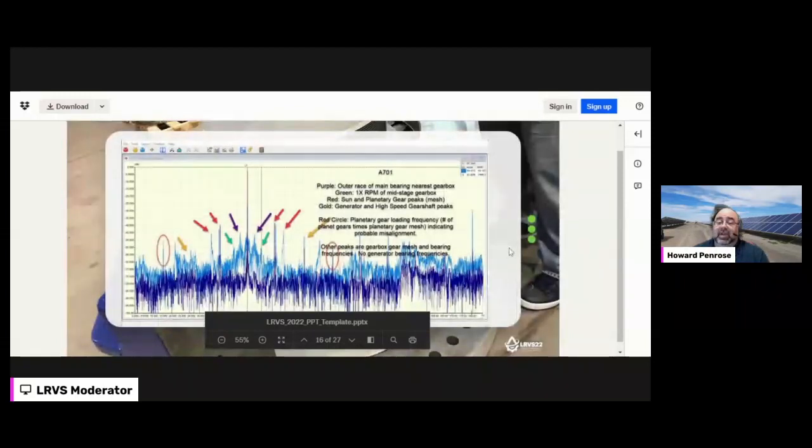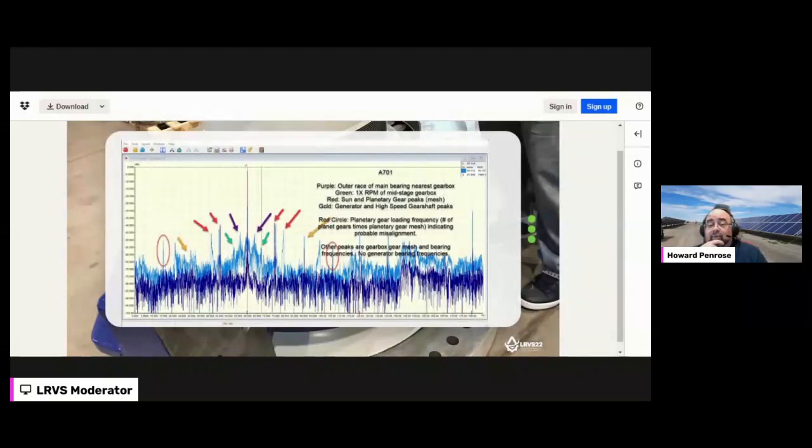And this is probably the worst turbine we've seen. It would operate for a whole 2 minutes, which gave us enough time to get data. What you're seeing is voltage and current laying on top of each other. Why? Well, it's a wind turbine. I have to look at voltage and I have to look at current. By definition, this particular design is both a generator and a load.